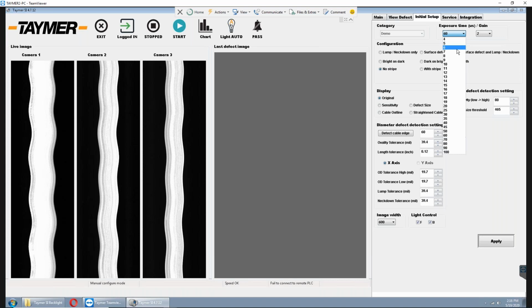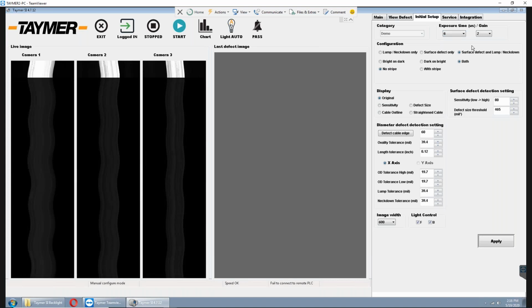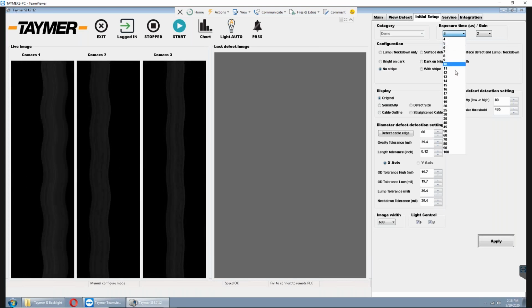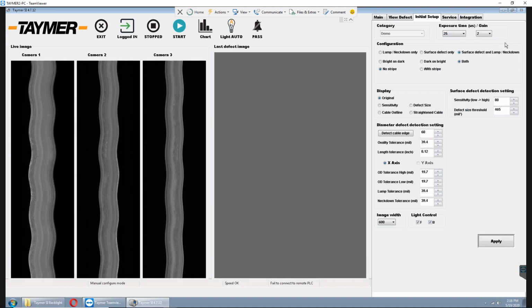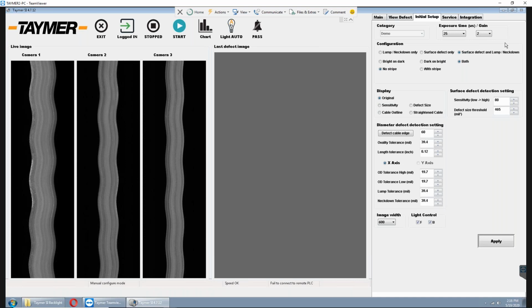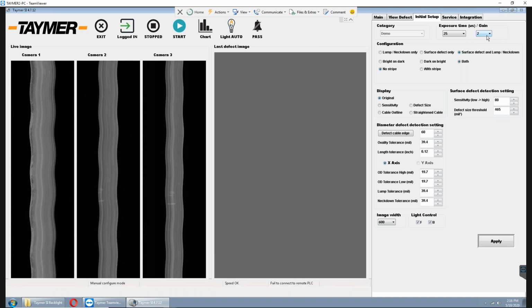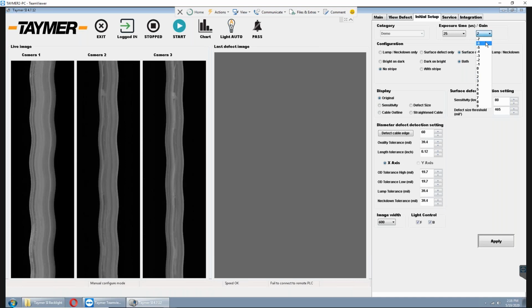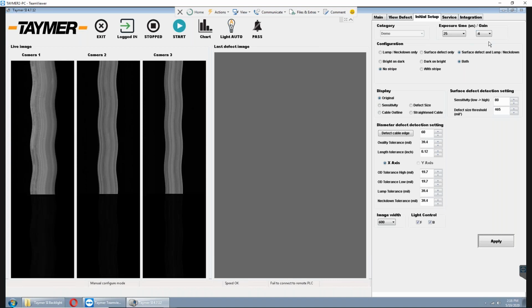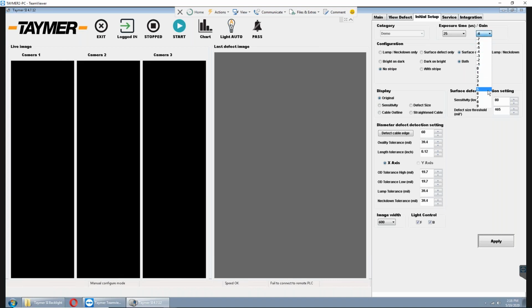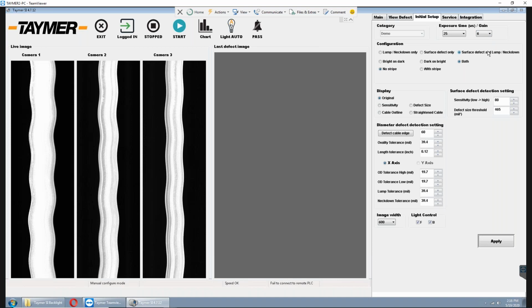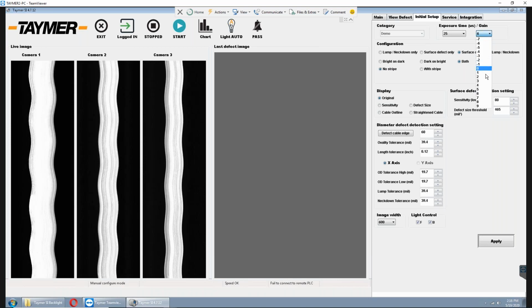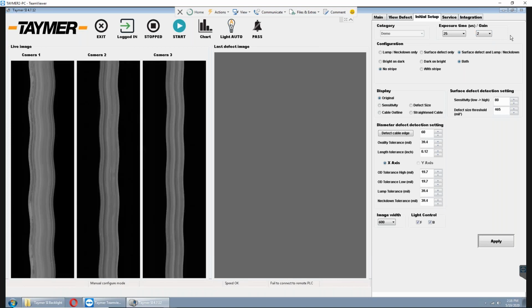And similarly, if I go really low, it's going to become very dark. This is the first thing that we adjust when you're setting up a new recipe, that exposure and gain. Similarly, the gain is basically just amplifying that signal. So if it's really low, it's going to become really dark. Again, high, it'll become bright. And so when you're setting up a recipe, that's the first step.